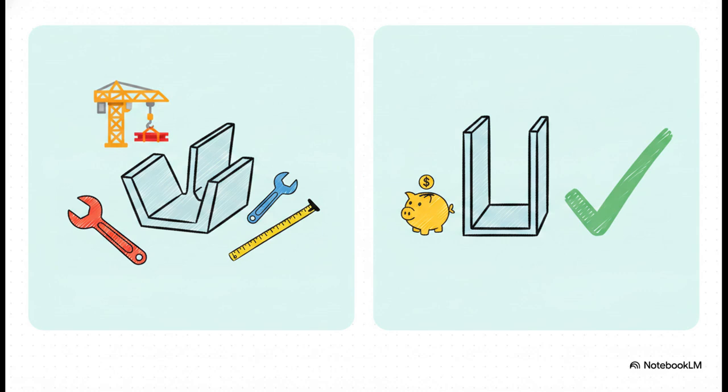You see, prior to this design, engineers frequently used something called a partial flume. The partial flume is fantastic, but it has a major drawback: complicated fabrication. It requires these custom downward and upward sloping sections that have to be built perfectly to spec. The cut-throat flume was a direct attempt to fix that by vastly simplifying the construction. By just sticking to a flat bottom and vertical walls, it becomes highly economical and incredibly easy to build, especially for small, straight irrigation channels. It's a real game changer.